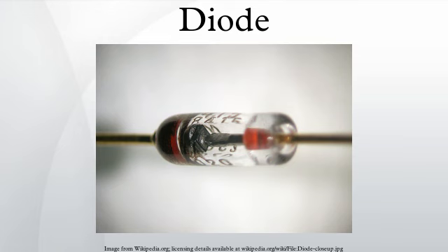If an external voltage is placed across the diode with the same polarity as the built-in potential, the depletion zone continues to act as an insulator, preventing any significant electric current flow. This is the reverse bias phenomenon. However, if the polarity of the external voltage opposes the built-in potential, recombination can once again proceed, resulting in substantial electric current through the P-N junction.